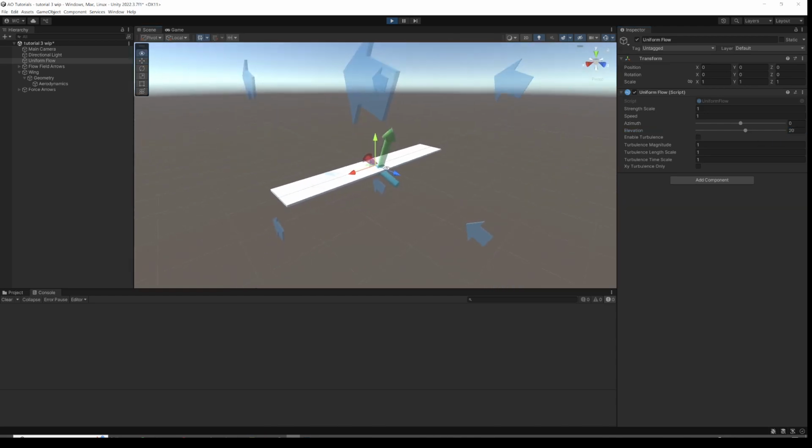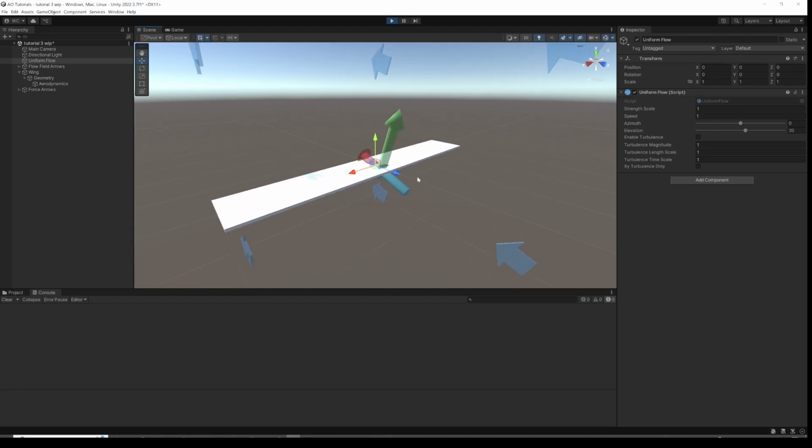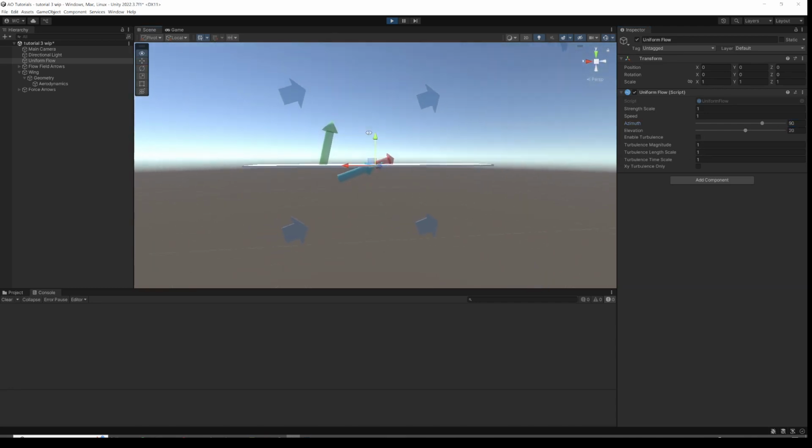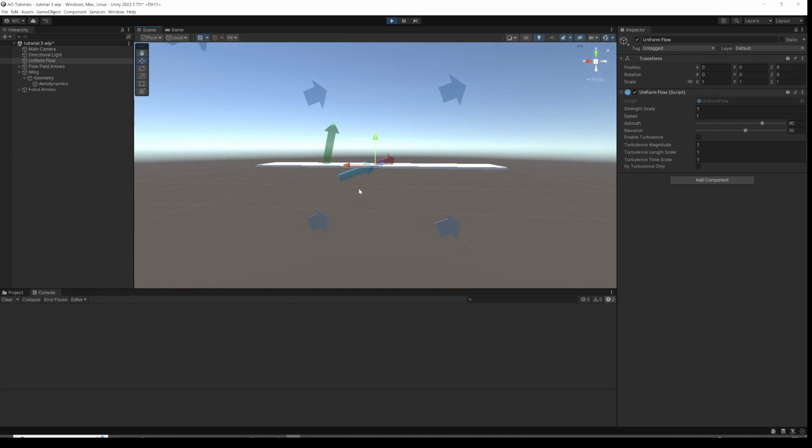And the other thing we're interested in terms of modelling things that fly, if this is a wing, it won't always fly that way. So it may start flying with the wind from the side. If you're a plane, you're flying in side slip. So how does the lift vary when you change the azimuth of the wind or the side slip of the wing? We can do this by varying the azimuth. So the wind is sort of coming from in the plane, and as we swing it round, if we get to 90 degrees, the wind is now coming straight up the side of the wing like that.